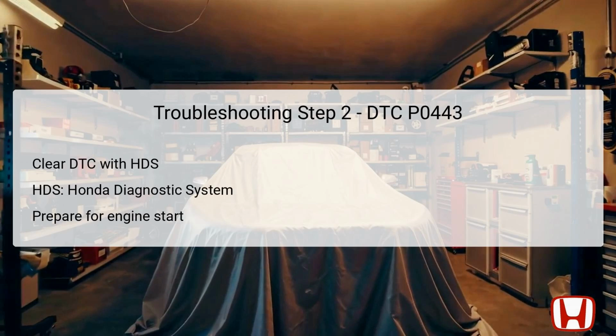Step 2 involves clearing the DTC using the HDS, Honda Diagnostic System. This step is crucial as it resets the vehicle's warning systems and allows technicians to start fresh diagnostics. By clearing the code, the system can identify if the issue is persistent or an intermittent failure.